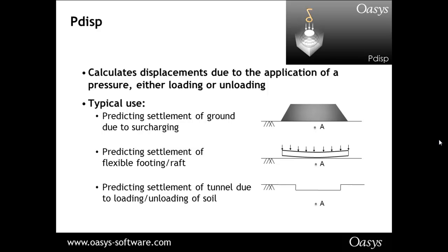It's also quite good for flexible footings or rafts, because if the footing is flexible enough that it moves with the soil, then you could really analyze it very simply using Pdisp, which is an elastic analysis. If you do have any kind of stiffnesses, then you should be looking at GSA raft.